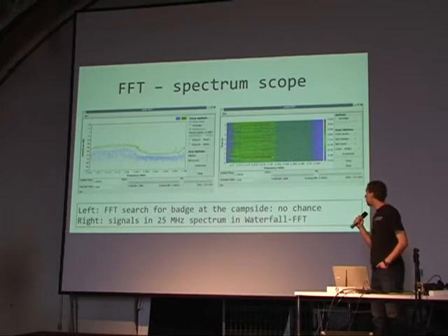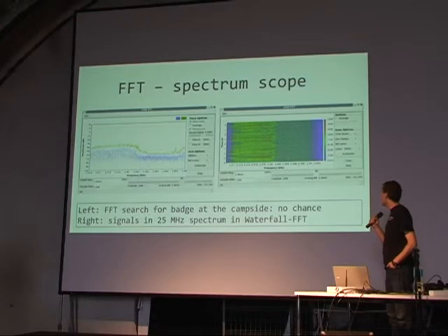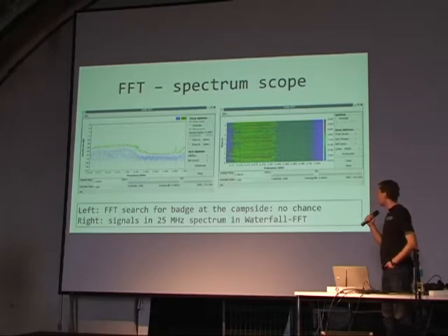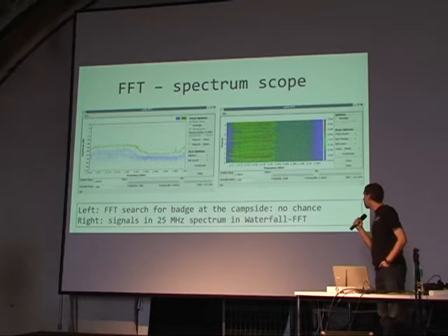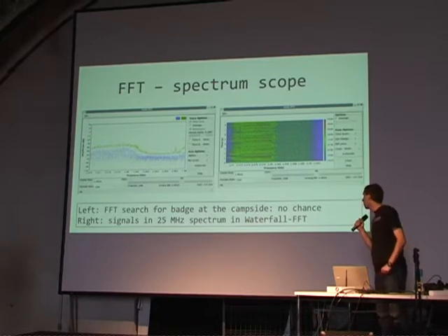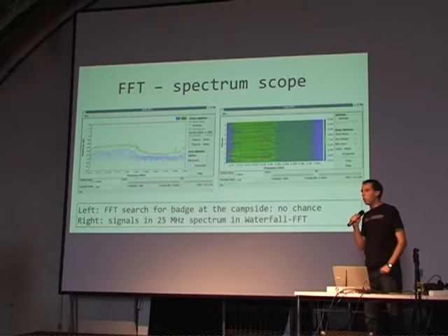So you see the green area to the left that marks that there was communication occurring in the frequency range from something around 2.47 gigahertz to 2.48, but there wasn't that much communication occurring from 2.482 to 2.492 gigahertz. So it practically shows that there is a divergence between the spectrums and it's practically a screenshot having a frequency range of 25 megahertz, which is the maximum you can do with the USRP2.